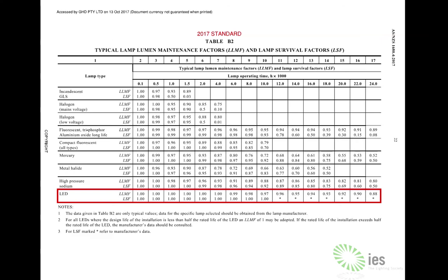When using occupancy sensors, do switching cycles on an LED impact adversely? It won't affect the LED chip. It may affect the driver depending on the quality of the driver. Ultimately the LED chip prefers to be cold, and that's all the LED typically cares about. But the driver will notice transient spikes, will notice harmonics, will notice your power factor, all that electrical side of things, including your switching, that's affecting your driver. Once it's passed through a driver and all it's getting is a constant current or a constant voltage, the LED doesn't care as long as it's cold.